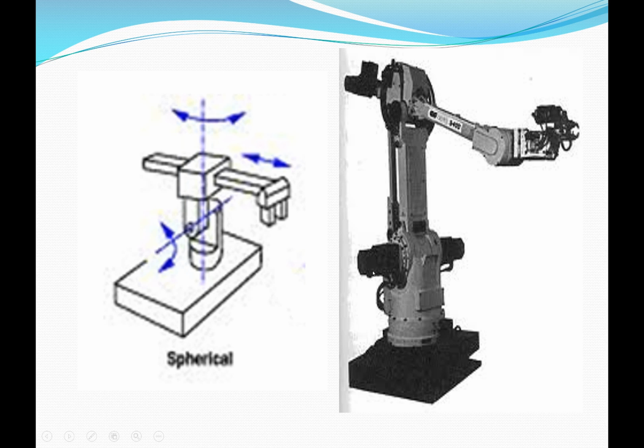As you look at this here: rotational, rotational, rotational, rotational, prismatic, because this goes in and out, right there. It's a little harder to see the prismatic here. If you look at this one here, you can identify which one is which, because this is showing rotational, this is showing rotational. Here's a prismatic. But this drawing doesn't show all the various joints on this particular robot.